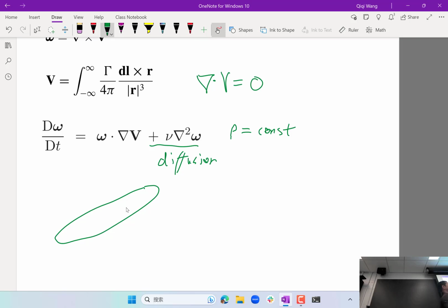That's going back to unified fluids: a wing, when producing lift, has circulation around it, and the circulation can be thought of as a vortex that lives inside of the wing. It's not vorticity in the fluid, but it's almost like imaginary vortices inside of the wing. So there is going to be a vortex that looks like this inside of the wing. What is the flow field induced by this bound vortex segment?